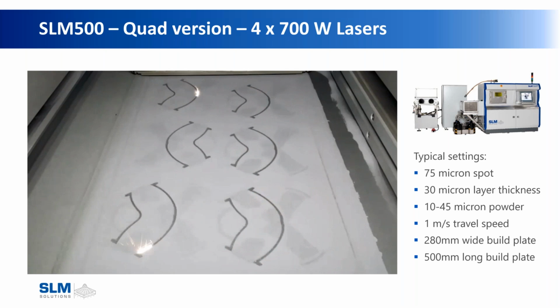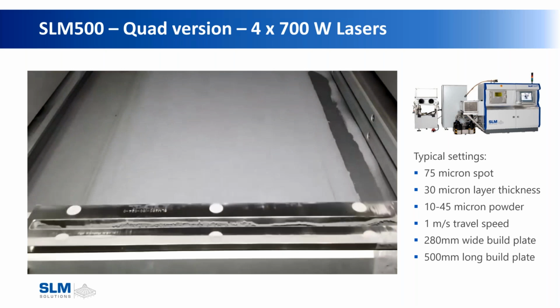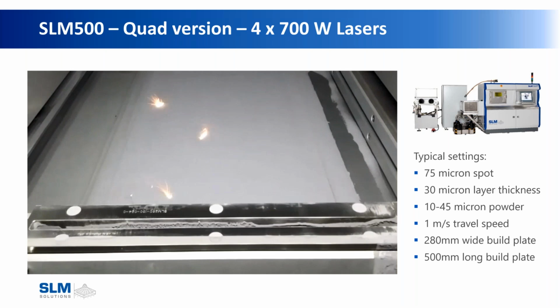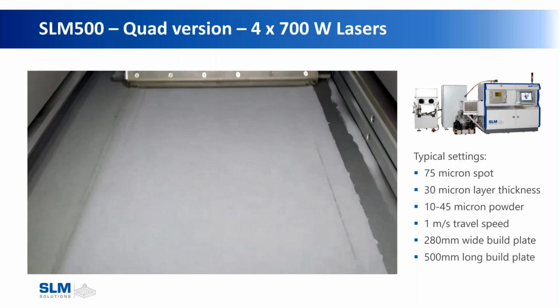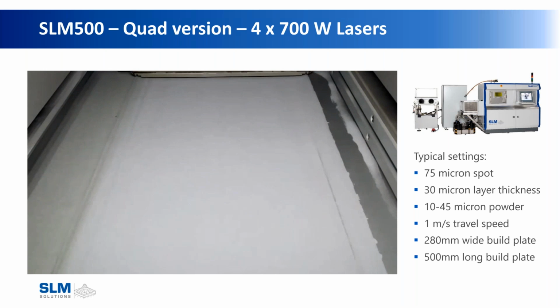And then the 90 micron is a very high pure casting replacement where we're going to have very high throughput, 3 times faster than our 30 microns, good quality, but your resolution may have dropped a little bit just because we're building one layer for the same that would usually take 3 layers. And as you can see with this video, we're doing bidirectional recoating. So every time that recoater moves, about 8 seconds, the machine is laying down a new layer and building a new layer of the part.